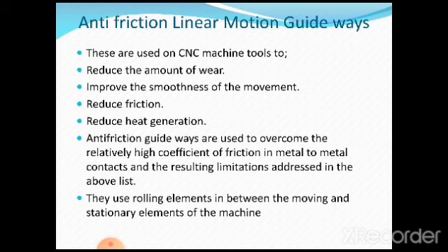Here you can see the cage very clearly, and the cage is used to guide the balls properly within the predefined path, so that whatever the rotation of the shaft, it in turn provides the linear motion to the moving element. This is very, very important.